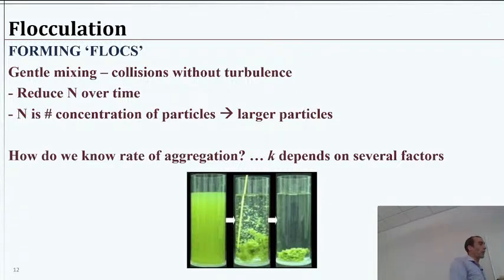And actually, this is quite common practice in water treatment plants to continuously have jar tests, or maybe once a day or a couple times a day, just to see whether the chemistry of the water has changed much. How much coagulant do we need? What's the optimum dose? Because sometimes if we have too much of it, it's not going to work as well, and if we have too little of it, it's not going to work so well. So in some combination, we need to say, all right, here's the right amount. We don't need to do all of the calculations about what exactly is in the water if we just take a jar of the water and try it. So it's quite empirical, quite simple, but also quite useful.